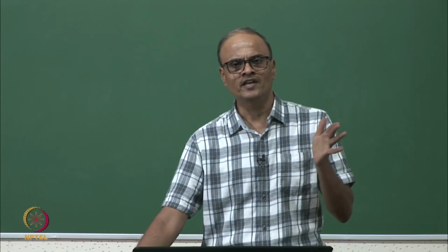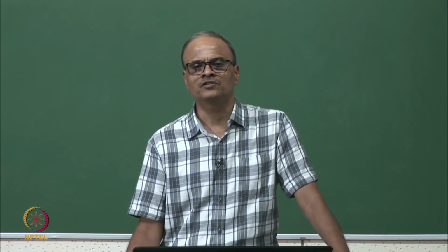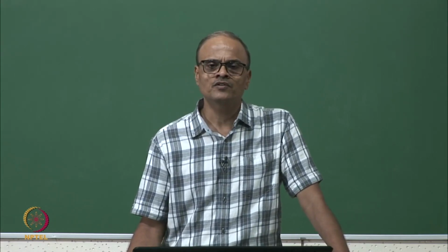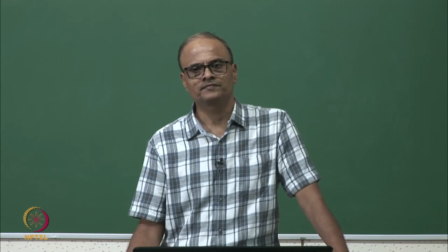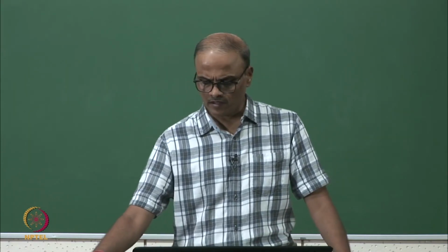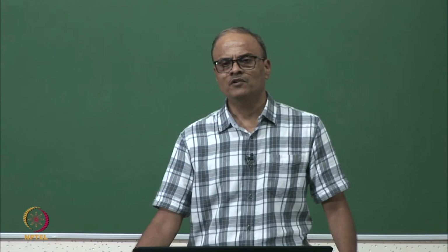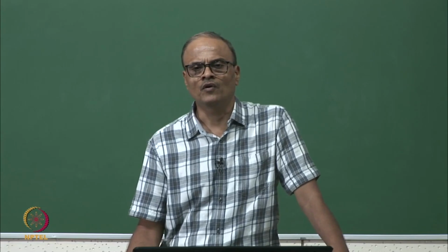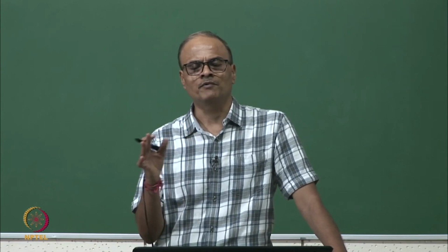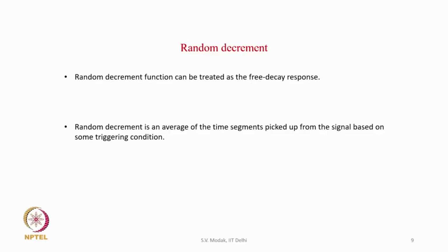Free vibration response decays with time due to presence of damping, and the correlation functions, because they also consist of damped sinusoids, are also like free decays. Let us briefly look at what is random decrement. Random decrement can also be treated as free decay response. The concept of random decrement was introduced to find a free decay response from a random vibration response, right. And random decrement is an average of the time segments picked up from the signal based on some triggering condition.